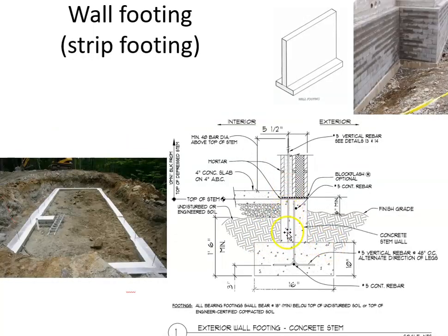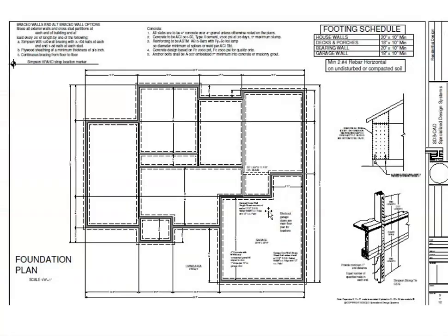So we're looking down at this wall, which is, we'd have to do a little math to figure out exactly how wide that wall is. I don't see it right there. Probably 8, whatever it is. We see the wall solid, and then we see the dashed lines of the footing, which is wider below. So let's circle back there. So there's our dark wall, dashed lines for the footing.